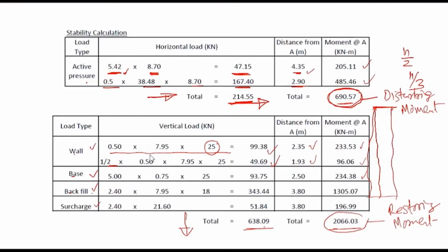So now we have calculated the moment about A, the active earth pressure, and the vertical restoring weight: the weight of the heel slab, the weight of the retaining wall, plus the weight due to surcharge and due to backfill above the heel slab. Now we will calculate the vertical axial load and the bending moment about the centroid, so that we can calculate the base pressure.